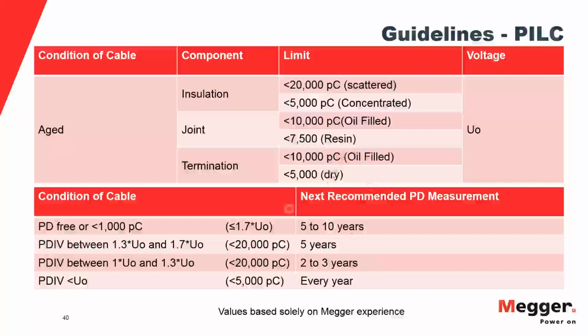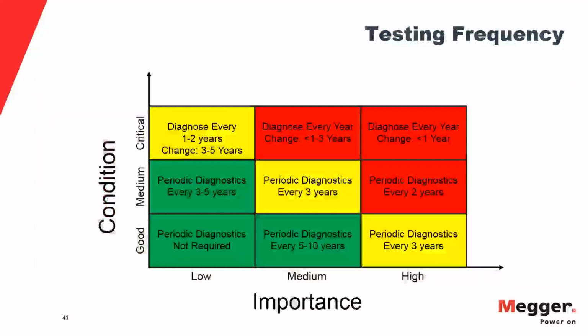Another piece of information that we use for partial discharge is that mapping. So how do we determine this mapping? That's a process we call localization. In this case, I have one particular partial discharge measured right here, and you can see it's got the arrow pointing at it, and the dot's slightly bigger. What we can see here is the initial pulse and the reflected pulse. I have a blue bar down here just to highlight the distance there.